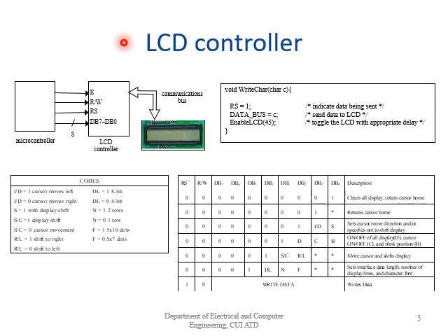So here you can see that we have the function enable LCD 45. The enable LCD function toggles the enable bit and also acts as a delay. So here we are toggling the enable bit, and also we are using a delay of 45.